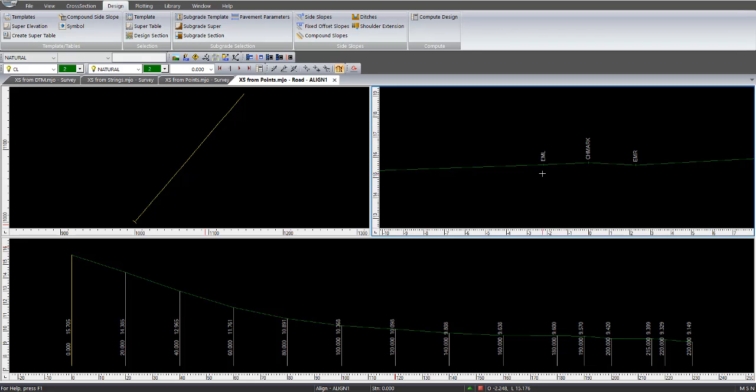The individual points that it selects out in the field will be displayed as the code of the point. So it's edge meter left, edge meter right. There was a string running along the left-hand side of the center line, which is that CH mark, and it happened to be edge meter left, and that's edge meter right. Same with that point there, the ground level shot.